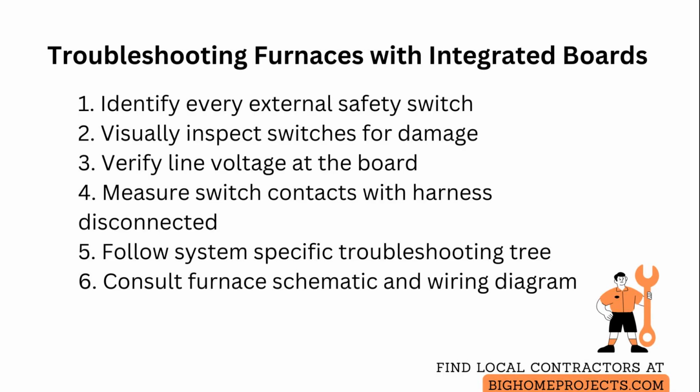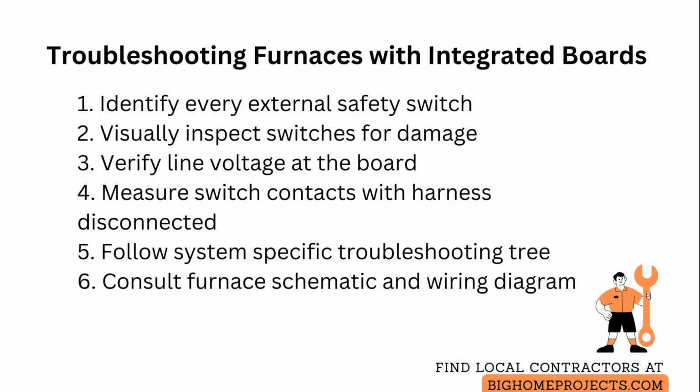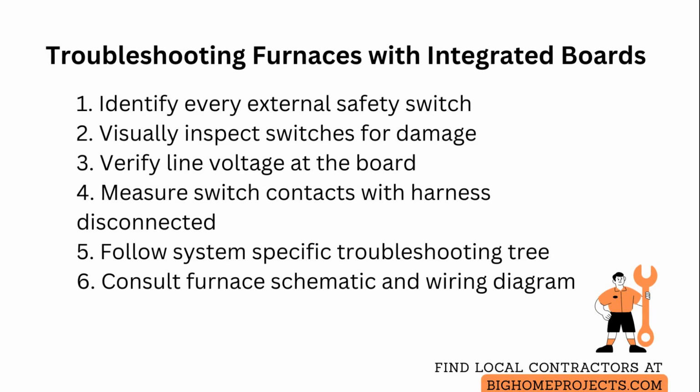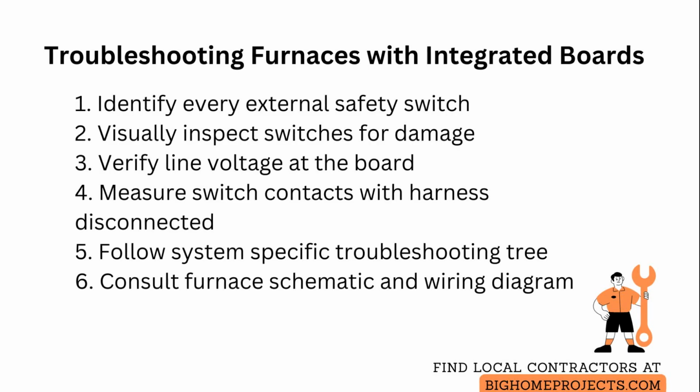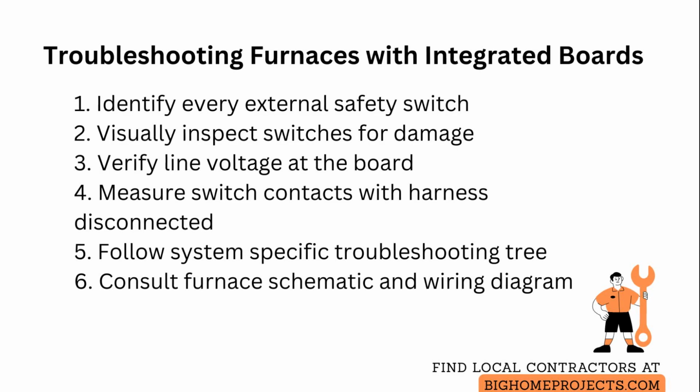Follow the system-specific troubleshooting tree that applies to your model because the integrated board may debounce inputs, require a specific sequence of operations, or report error codes that guide the next steps. When in doubt, consult the furnace schematic and component wiring diagram. These show which pins correspond to each safety input and whether the board expects normally closed or normally open devices.